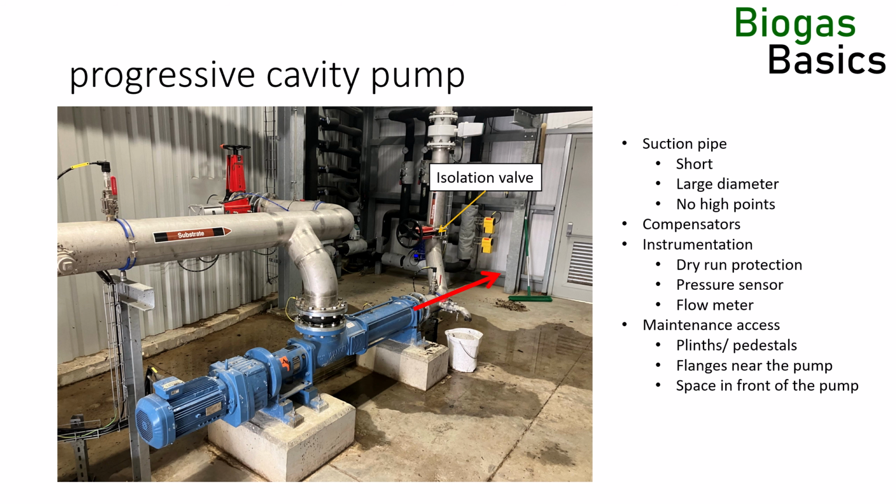In this picture here, the valve at the discharge side can be closed and the short pipe piece removed, and the stator can be pulled out of the pump without any pipeline in the way. Above the pump, and not seen in the picture here, is an I-beam with a chain hoist to lift the pump up and transfer it to a small wheel loader.